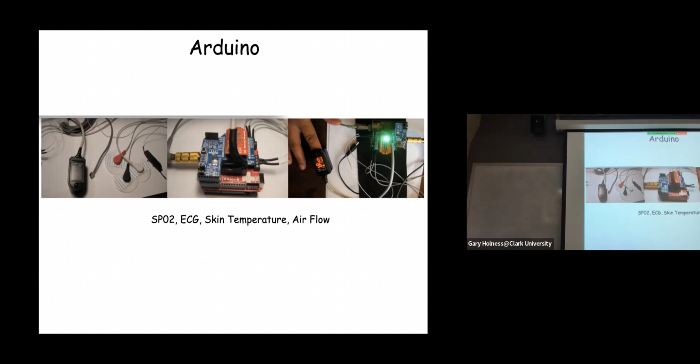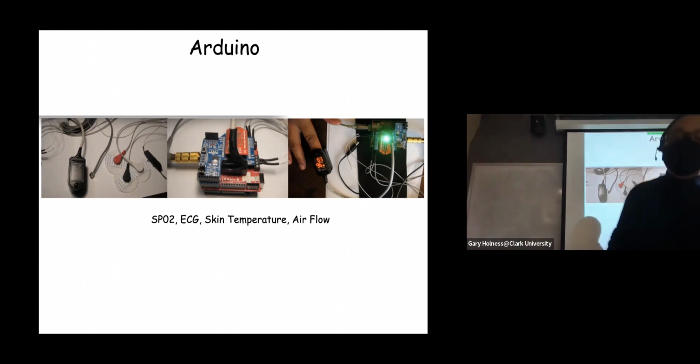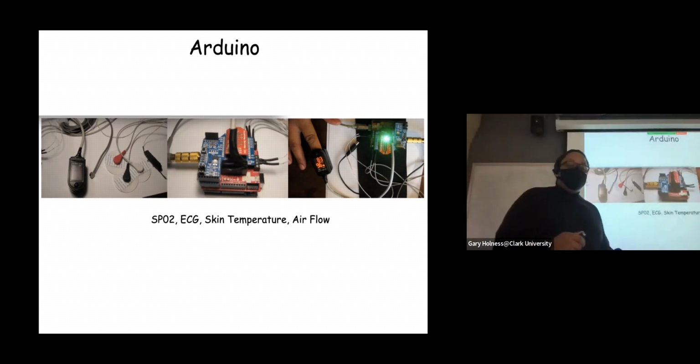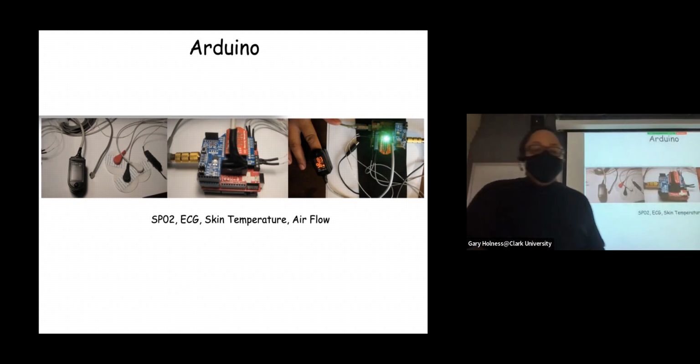So you place a sensor over your heart and another sensor someplace near your heart. And that difference in the flow of ions has a potential or voltage that's measured as your heart signal. And so there's that characteristic heart signal that kind of goes across, you see on all the medical shows. And so we have ECG, we have skin temperature, which goes under your armpit, airflow. So a couple of things.